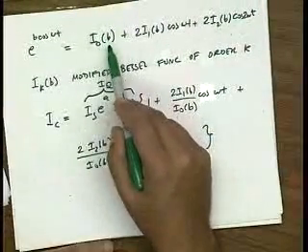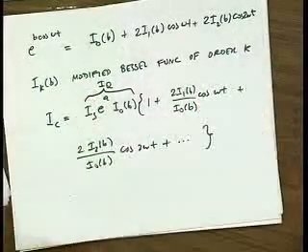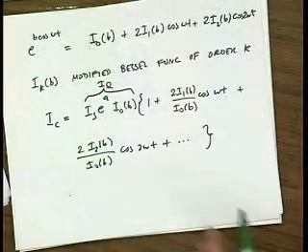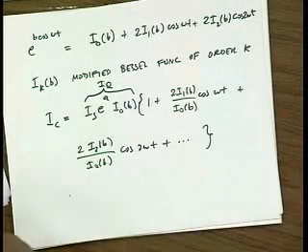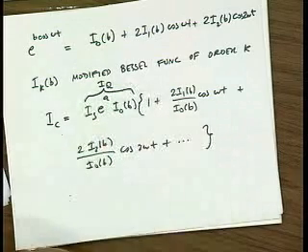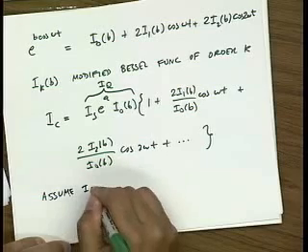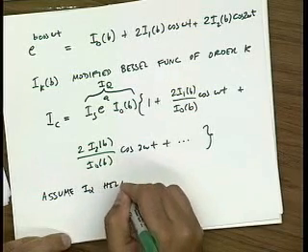I0 as a function of B actually will increase. We already know that. We know that all second order nonlinear terms generate DC. So the DC level of the circuit would shift. But in reality, I'm actually going to have some external circuitry to keep IQ constant. So what I'm going to do here is assume IQ held constant.